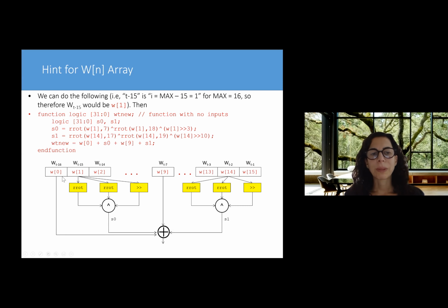What we are doing is just using these inputs selectively, like the W1 here, which goes through these right rotations, as you see here, and then it is going to get shifted, and then the OR function is going to OR them, and this creates the S0. S1 is similar. It's going to use this W indexed here.